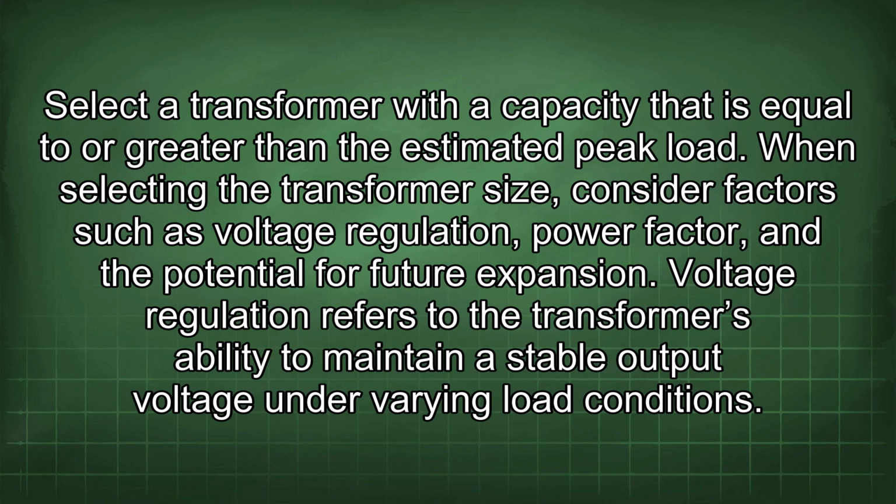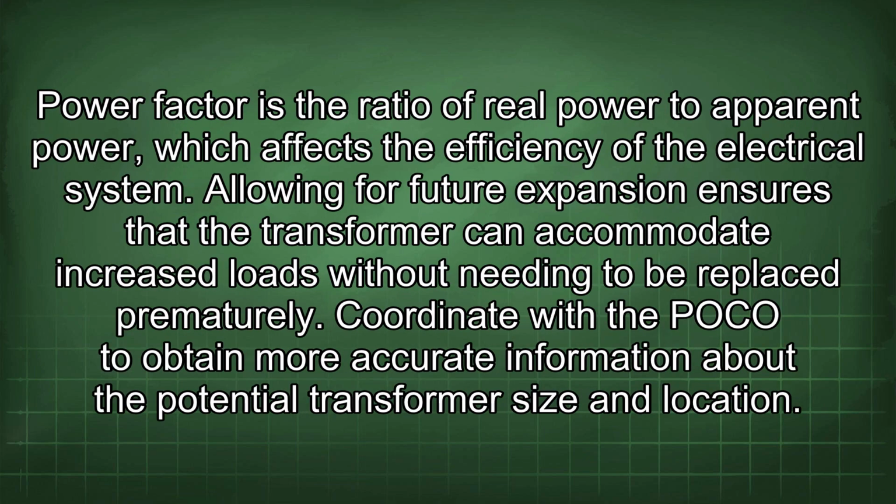Voltage regulation refers to the transformer's ability to maintain a stable output voltage under varying load conditions. Power factor is the ratio of real power to apparent power, which affects the efficiency of the electrical system. Allowing for future expansion ensures that the transformer can accommodate increased loads without needing to be replaced prematurely.